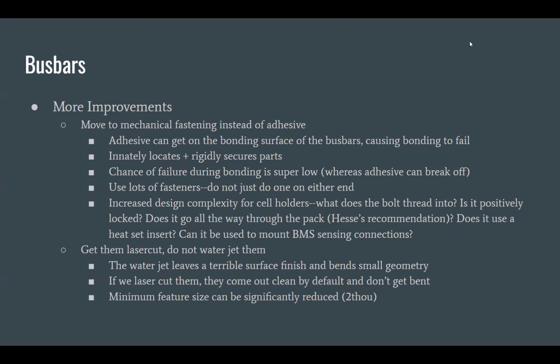We also want to use as much space as you have, and then also your electrical constraints. So your configuration of number of cells, kinds of cells, series versus parallel, and stuff like that. As you play with what those different configurations could look like, you'll come up with a bunch of different designs based on these space constraints, and then you can work on different packing structures and start to narrow in on an initial cell holder. Starting with your electrical and overall space constraints is a good place to start.